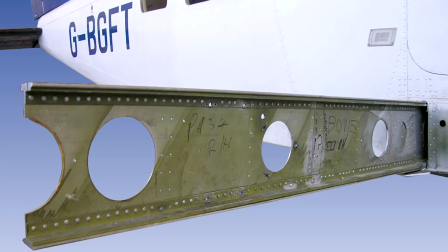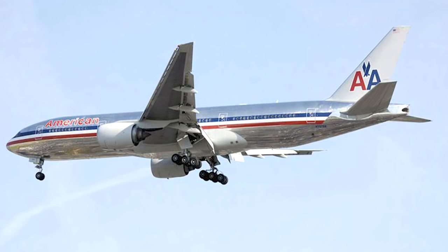Aluminium alloys are the most widely used metals for structural use, due to them having a good strength-to-weight ratio. Duralumin is an aluminium and copper-based alloy, which has poor corrosion resistance, except when clad with pure aluminium. It has good thermal and electrical conductivity, and good fatigue resistance, but it is difficult to weld. Aluminium-clad duralumin is the most popular material in use for airliner skins.